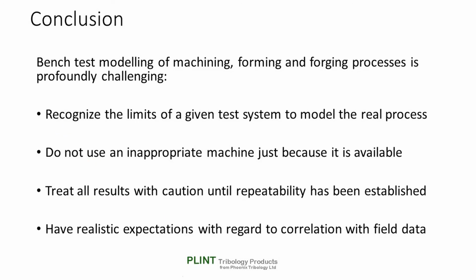To conclude, when it comes to modelling machining, forming and forging processes in a tribological experiment, there are no easy options. You must recognize the inherent limitations of a given test regime. Do not use inappropriate test machines and test geometries just because they are available. Treat all results with caution until repeatability has been established, and have realistic expectations with regard to what can be achieved in terms of correlation with field data.